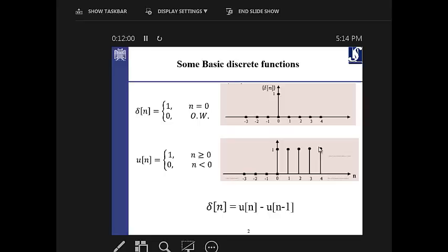But during representation of the signal in the discrete domain, we normally hide that. We ignore it. But ignorance doesn't mean that it doesn't exist. It is somewhere just behind what we're writing down. So we are somehow forgetting about the time or frequency of sampling, but it doesn't mean that it's not existing there. So when we talk about these discrete domain signals, we have to take care about the frequency of sampling. That's an important thing. Even though it's a sequence, the same as what we have in mathematics, the samples are actually representing time samples, but that time is hidden. It is assumed to be known. I think you get the meaning.